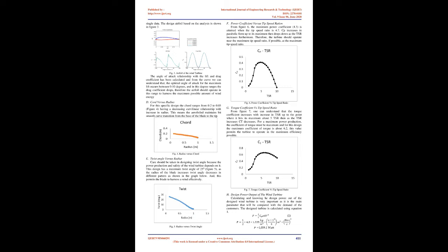The geometry plot contains all the relevant information about a candidate blade's geometry, Fig 1. The curves are manipulated by control points and they define the blade twist and chord distributions. The dimensional thickness, twist, and chord decrease as the non-dimensional radial position of the blade, r/R, increases. From this graph, one can easily understand that the optimal CP will be derived considering all four relationships, and the CP value is about 0.47, and this is shown in section 3F.